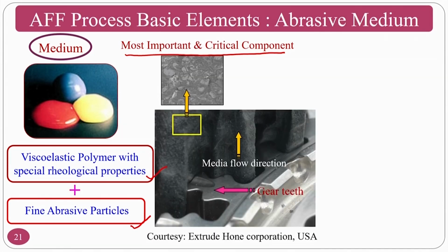what are the rheological additives that people normally use? Many types of viscoelastic polymers are there, but commonly used is polyborosiloxane. Many of the companies which commercially produce this polymer are one of the best examples of a viscoelastic material, and this material is blended along with many rheological additives such as softeners, plasticizers, hardeners, functionalizers and so on. If you are going for a low viscous type, then they add the functionalizers for holding the abrasive particles in location, so many additives are used.